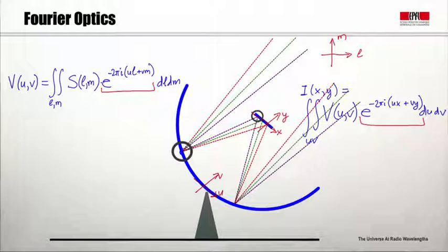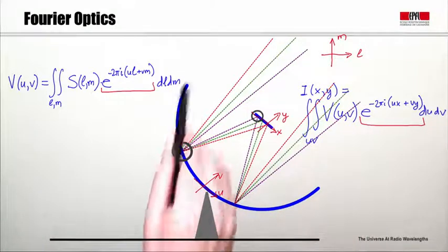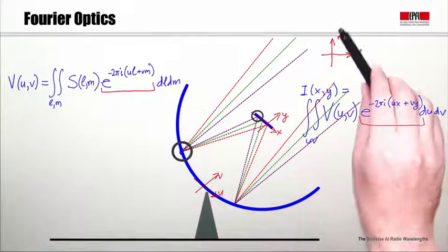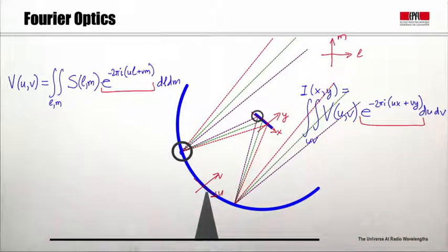So the premise of aperture synthesis is actually very simple. We measure the field in the aperture plane, where it's a Fourier transform of the sky, and then we do the second Fourier transform in software, and that recovers the sky image for us.